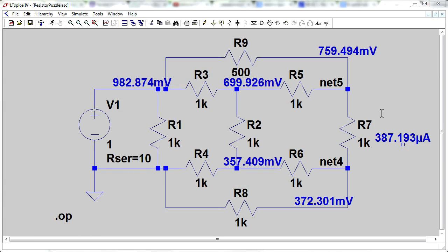And let's say we wanted to display something simple like the voltage across R7 here. Well, that's not as easy as in some other circuit simulation programs. Some of those simpler ones for beginners might have a multimeter tool, and you drag in the multimeter. It has a little multimeter display and little probes, you hook it up across R7, and you can measure the value across that. But LTspice isn't catering to that sort of ultra beginner market. It's more your professional, traditional SPICE circuit simulation.